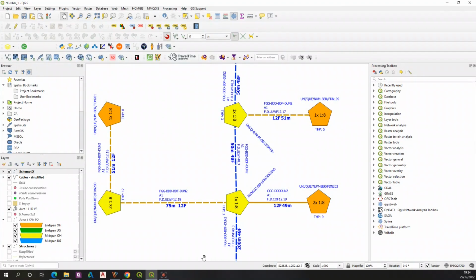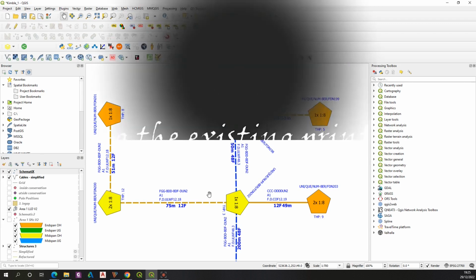So, since we have the problem with the scale finally sorted, we can go to the next step, which is generating the PDF document from our work. Basically, if you are not savvy enough with QGIS, it can be quite a significant problem, as we have quite a lot of options to set here, but everything is doable, so don't worry.